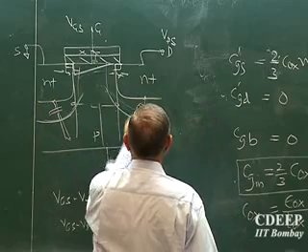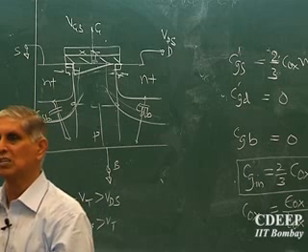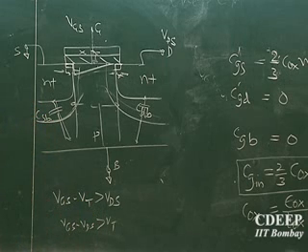Sorry, I should put capacitance. And how will you calculate these values, CSB and CDB? Assume a step junction for this value of voltage for the given doping of substrate. N plus P is a step junction, so N plus you forget about it. So only P side depletion. So evaluate W is equal to under root twice Ks epsilon by QNA into voltage. In the case of source, it is only 2 phi F. In the case of drain, plus VDS value you have to add, figure it out, then find CSB and CDB.